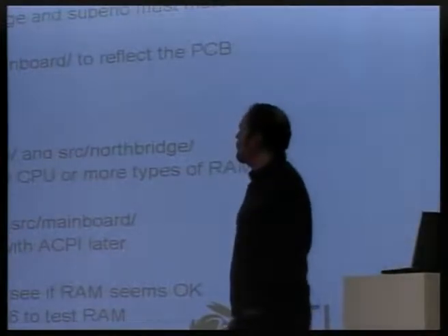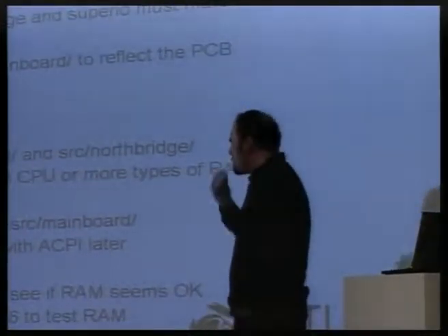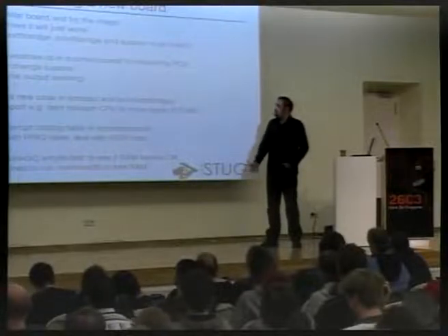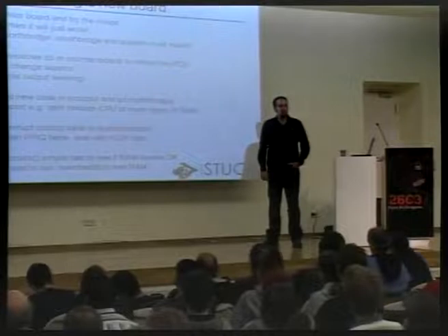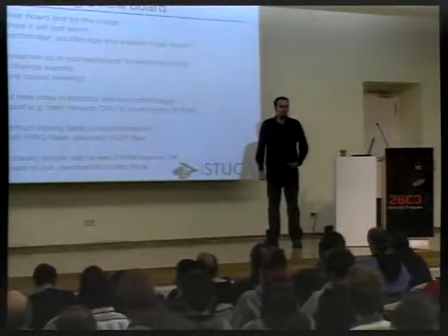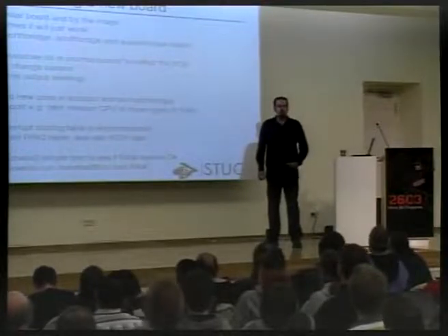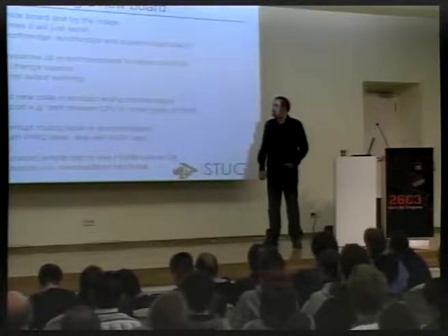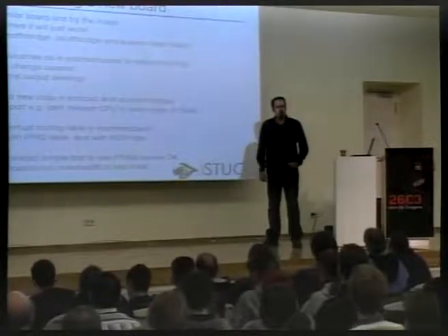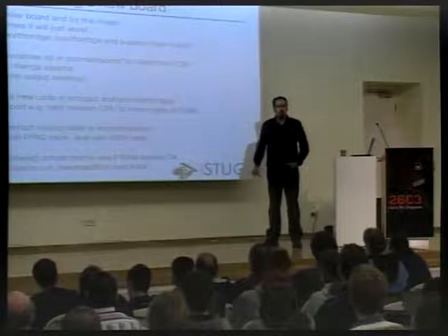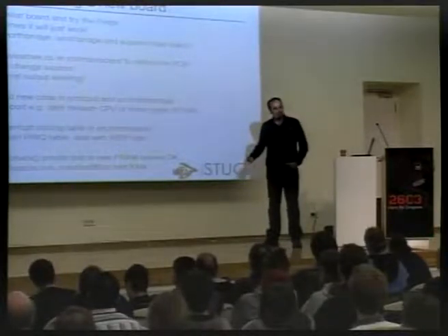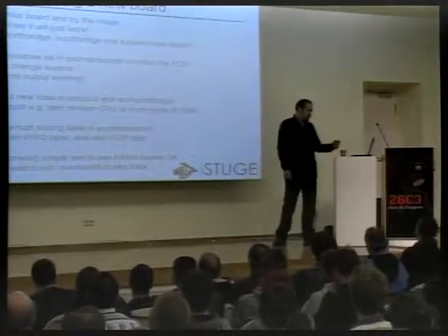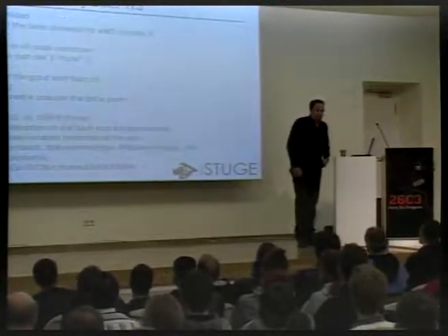So sometimes we get some mails on the list where someone has tried to boot a new board, and it looks like coreboot is doing everything okay, but the payload doesn't work or doesn't start, and that usually indicates a RAM problem, because there's a lot of caching going on, and it could be that all the code is running from cache, so that there wasn't any need for RAM until the point where the payload is supposed to be started, and then it blows up. So yeah, setting up the memory controller is by far the biggest problem.